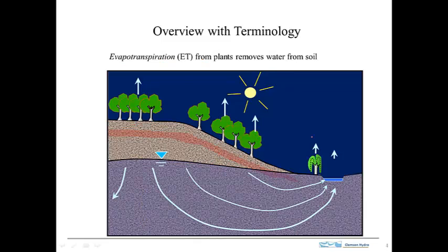What's going to happen now is the evapotranspiration process is ongoing, but I want to focus on the water table and what's happening there, because this process of flow that's being shown here is ongoing. There's water flowing in the stream, even though maybe it's been quite a long time since it's rained. There's water flowing in the stream, and that's because the groundwater is discharging up through the stream bed.